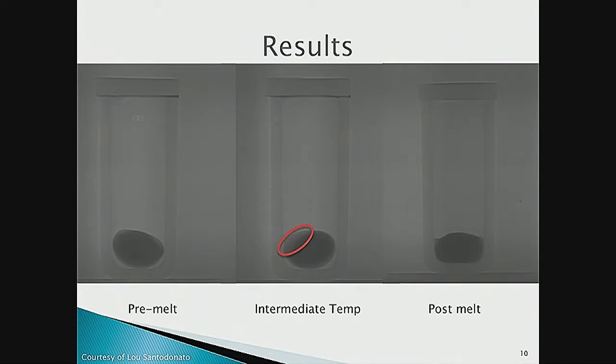So before they melt, or I guess we help melt these samples, we saw our alloy right here. If you look really closely, I know it's dark, but you can see a little bit of a lighter structure right there. That is our copper-rich phase. The darker part is more of our cobalt, less transmitted. And so once we heat it up, we can see the copper phase start to melt a little bit. It's moving around. It's starting to flatten out.